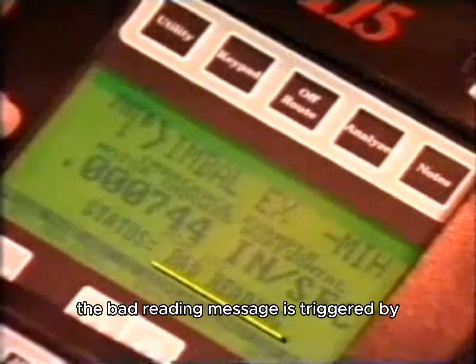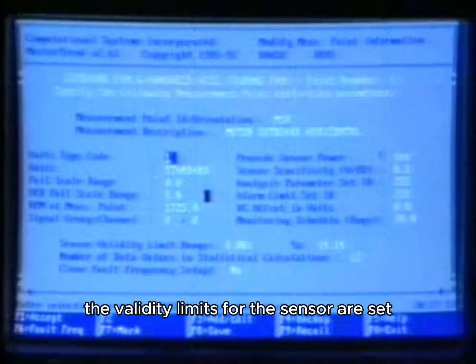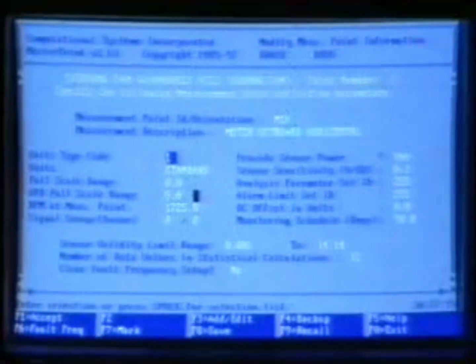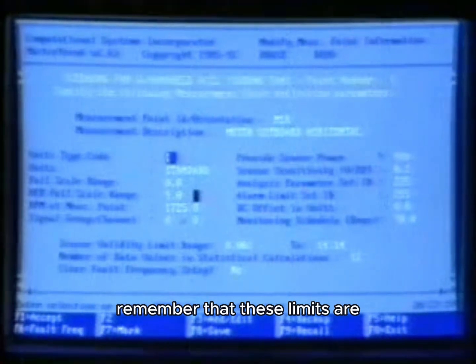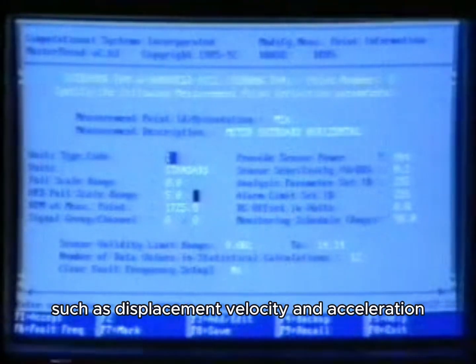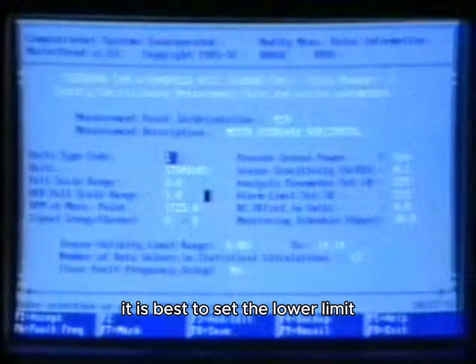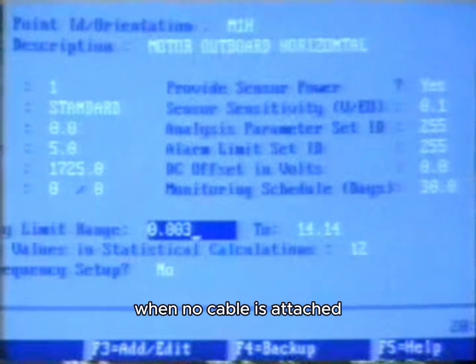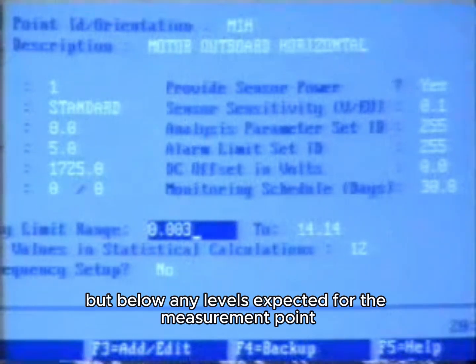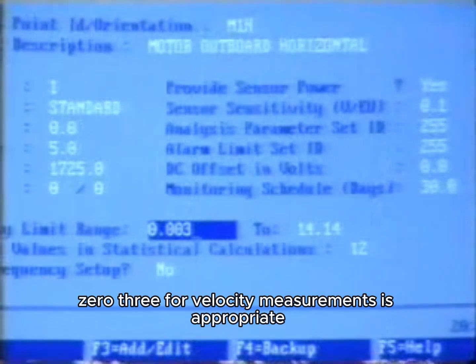The bad reading message is triggered by the value specified for the valid range of the sensor. The validity limits for the sensor are set in the measurement point definition. The limits can be set for the upper and lower limits. Remember that these limits are the output units of the transducer, such as displacement, velocity, and acceleration. It is best to set the lower limit above the value recorded by the analyzer when no cable is attached, but below any levels expected for the measurement point. Usually 0.003 for velocity measurements is appropriate.